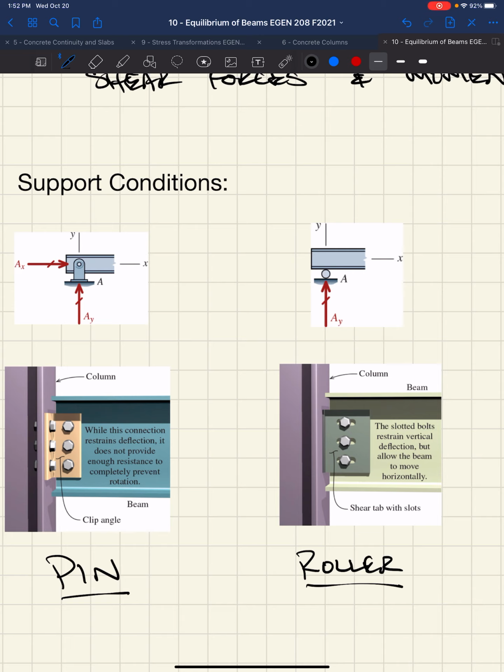It is cool. Concrete is a terrible building material. It's not a terrible building material, I just don't like it very much, but it's not very good in tension. It's essentially a ceramic, like glass, so it's very good in compression but very bad in tension. So we end up putting steel in it, which is the most beautiful building material known to humanity.